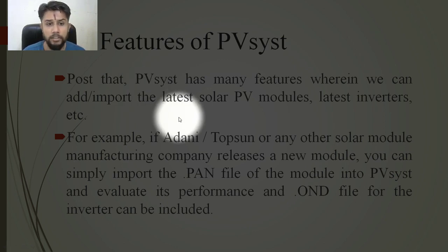Suppose you find any module which is not listed in the PVsyst software, you can incorporate the .pan file of that module and similarly the .ond file for that inverter, and with this you can check the compatibility of this module or that inverter for your purpose of generation, for application purpose, for system performance evaluation, for comparison purpose, for analysis purpose. So this is the best feature that PVsyst is offering.